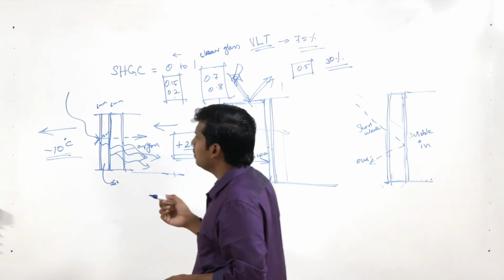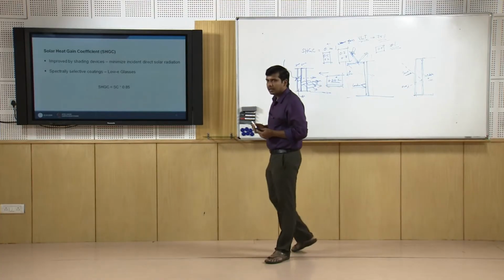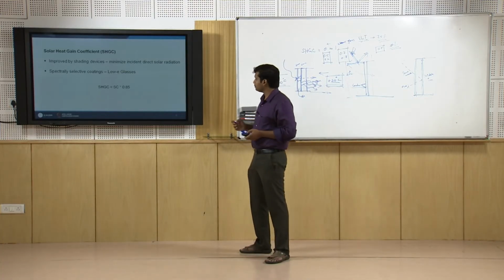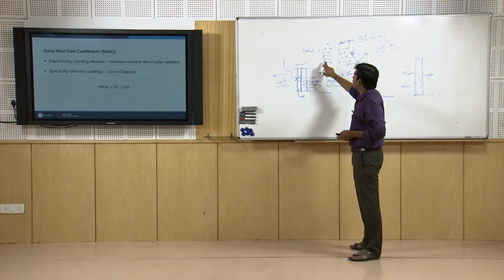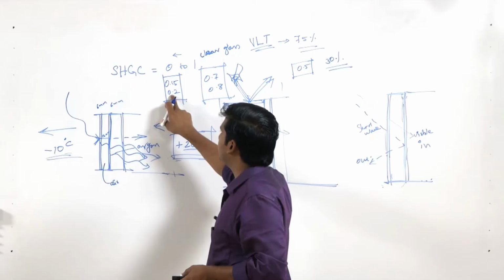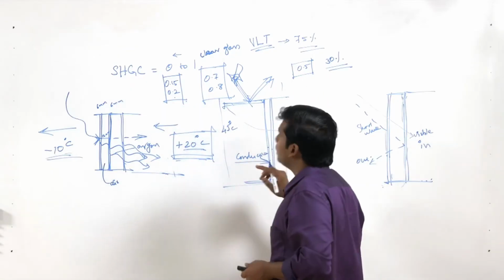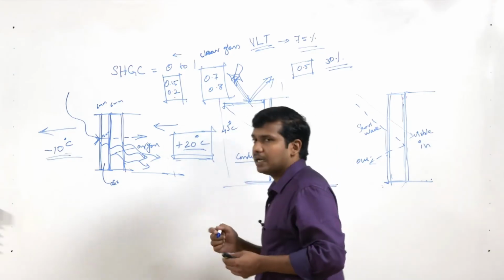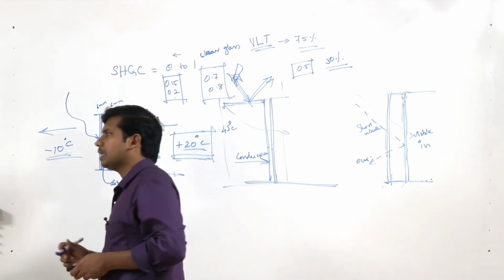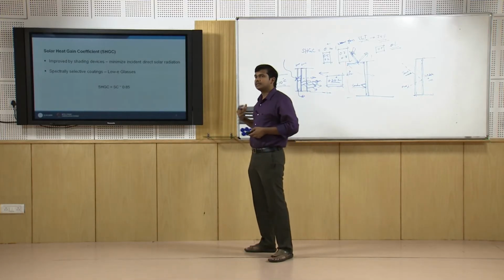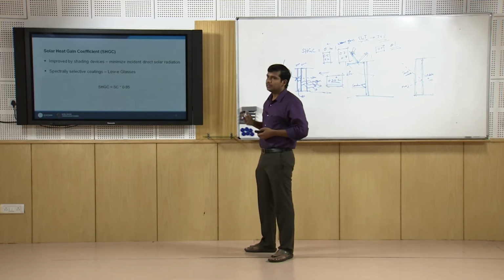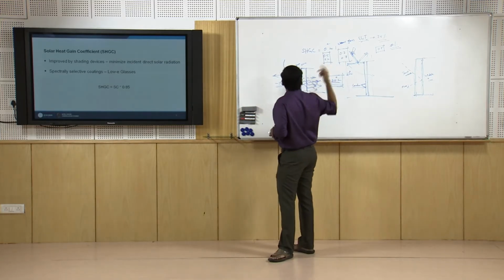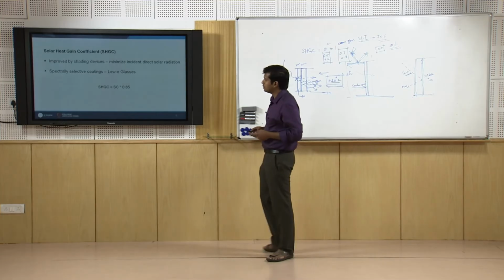On the other hand, when you use a low E coated or a spectrally selective glazing, this does not happen. Even for a glazing with 0.2 SHGC, you may be able to get a VLT or visible light transmittance up to 50-55%, or with modern day coatings it can even be higher. It depends on the type of products or the coating material which is used.